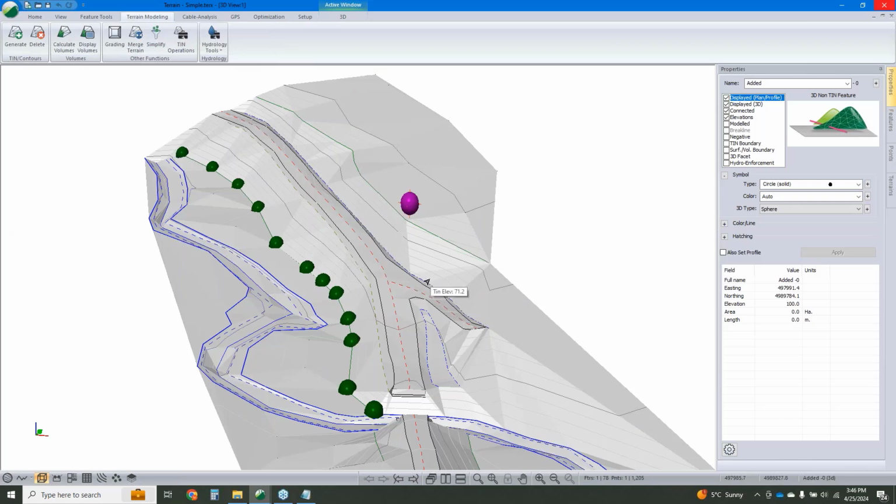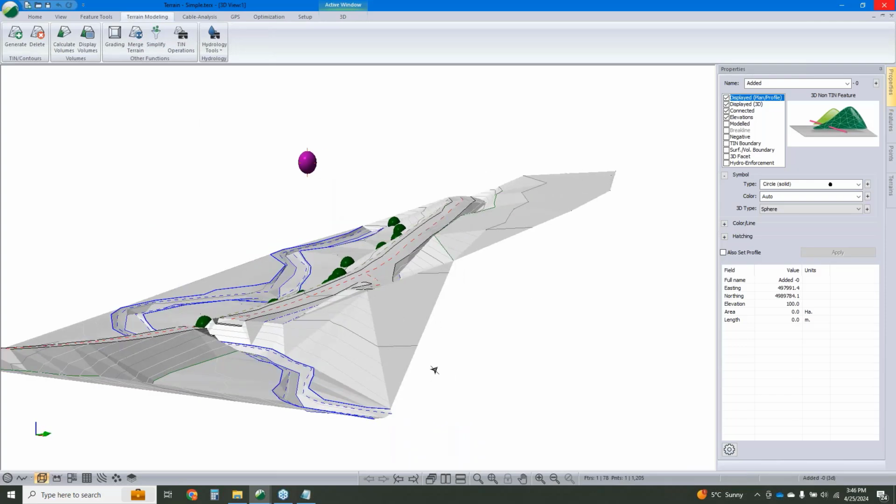conventional survey data here, but even if you're working with LiDAR data and you bring in a feature and you turn model property on, maybe that feature was originally a 2D feature, well, you might get holes in your model going down to that feature that you actually don't want included in your model. So there it becomes important to just, oh, I don't want that to be modeled, select it, turn modeled off.